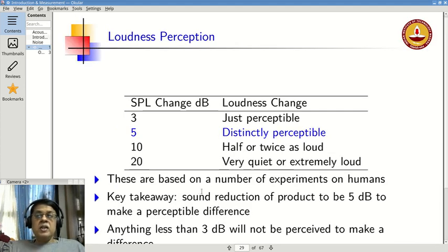So what does this mean? Just quickly to give you, even though in reality a 3 dB change is actually, if you look at the amplitude, it has dropped by half. So if I reduce by 3 dB, so let's say I go from 82 to 79, you go back, work the calculation, you see that my pressure amplitude has come down by 0.5. So it's a significant change. You will think, I have brought it to 50%. But interestingly, if you ask someone, they say, okay, yeah, I think there's a small change, but maybe a little bit, but not so great, right?